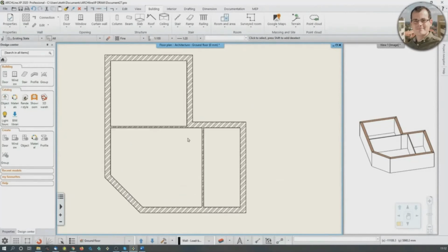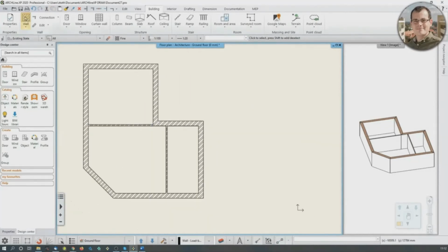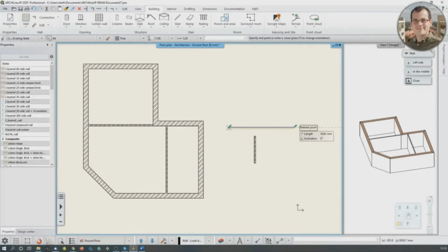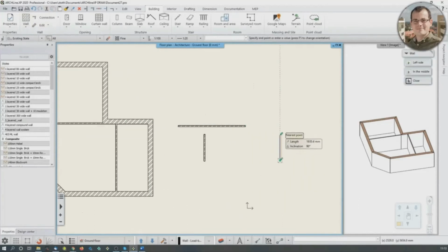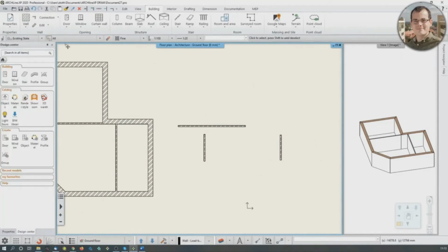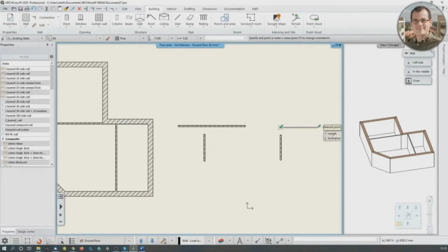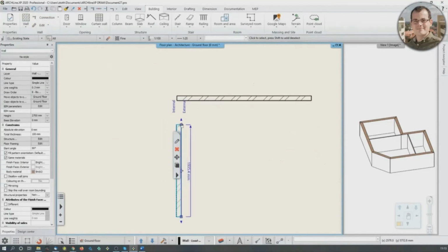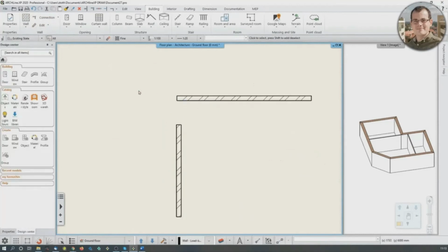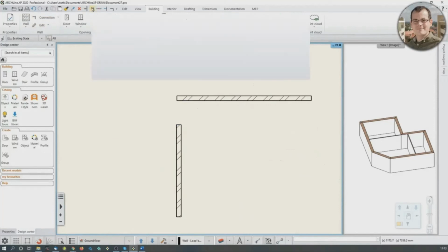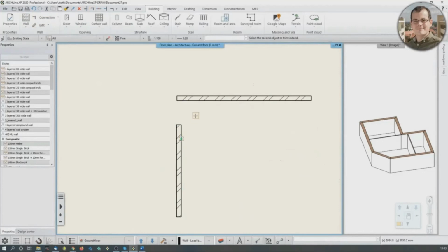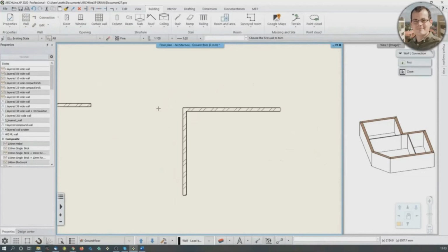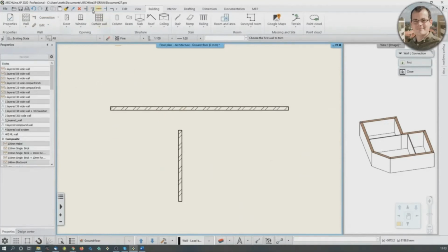Now the wall connections are good, but let's assume that you have a much more complicated drawing than that, and you have wall connections which are not getting together. So let's say you have two walls like this and another two sets of walls like that. If you want to have an L connection connecting these walls together, you can click on the wall and extend its length, but the very interesting and easy way to do it is with these menus. L connection, for example, I just click on this, click on one of the walls, click on the other wall, and then the two walls are going to be extended. If I want to have a T connection, then I use the same tool, only this time it's going to be a T1, the wall which is going to run into the head of the T.